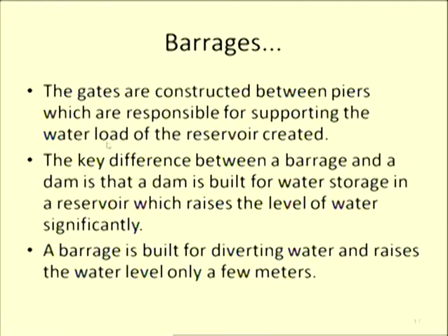Between the piers, which are responsible for supporting the water load of the reservoir created, the key difference between a barrage and a dam is that a dam is built for water storage in a reservoir, which raises the level of water significantly, very high. A barrage is built for diverting water and raises the water level only a few meters. A few meters here could be 10 meters, 15 meters approximately. So that is the big difference, that gates are lowered to raise the water and that water is diverted.